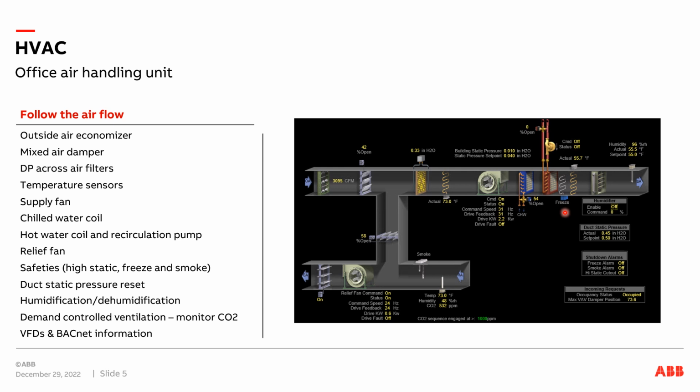Last thing I want is my coils to start freezing up because I'm blowing minus 20-degree air through the air handler, and coils freeze, ice expands, things break. Not good for anybody. So you have freeze stats here that are safeties that say, hey, something is wrong. It's way too cold in this air handler. Let's shut everything down. So that's what your freeze stats are.